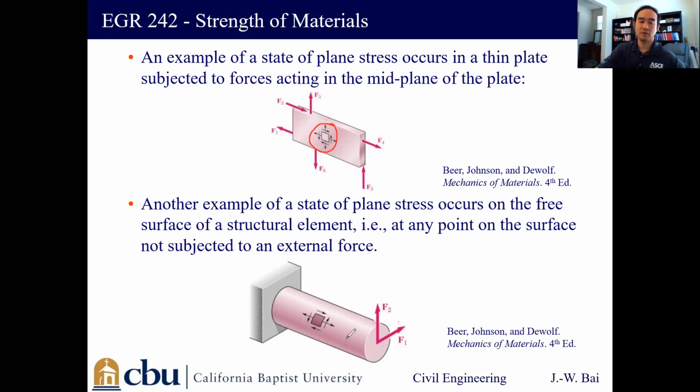This is another example: the surface of whatever your structural element is, and here we have a circular rod, or a cylinder type of structural member, and we apply the forces here. And think about the stress block at a point on the surface, okay? Due to the external forces here, we will have stresses parallel and perpendicular to these two directions, but not perpendicular to that surface direction, okay? So we can simplify it as a plane stress condition.